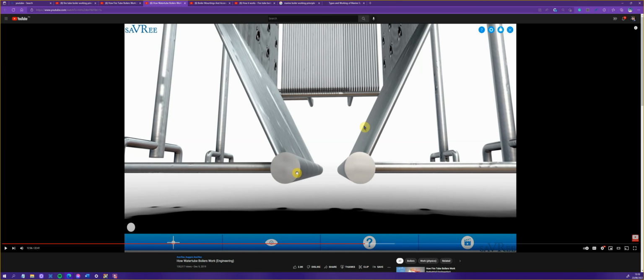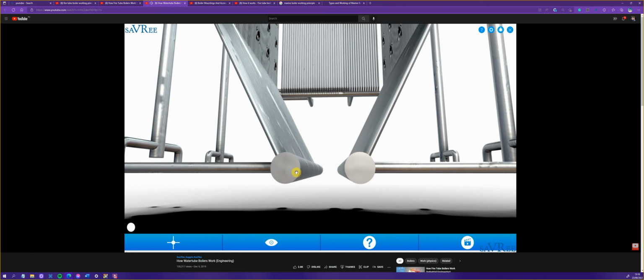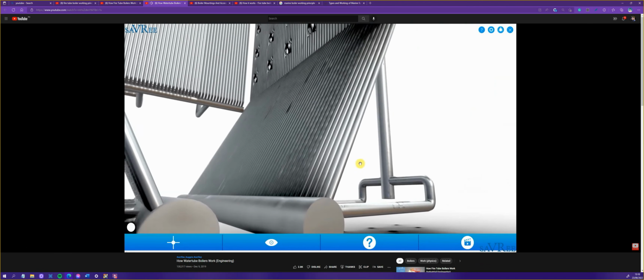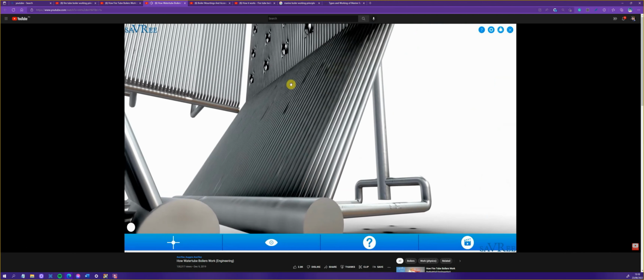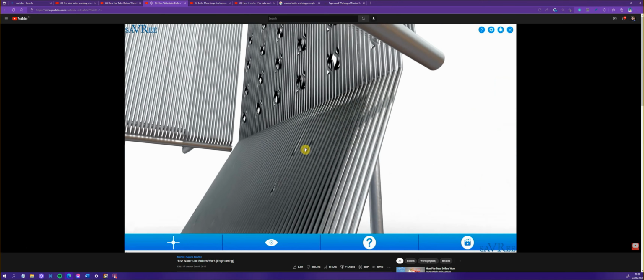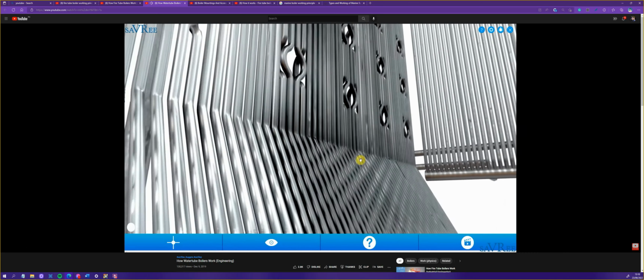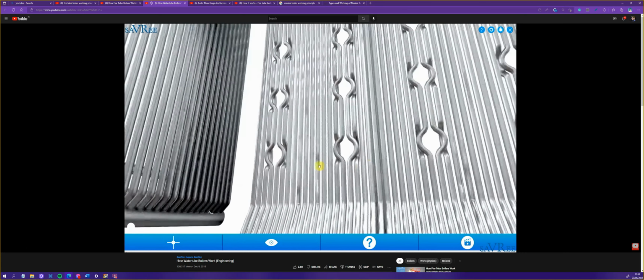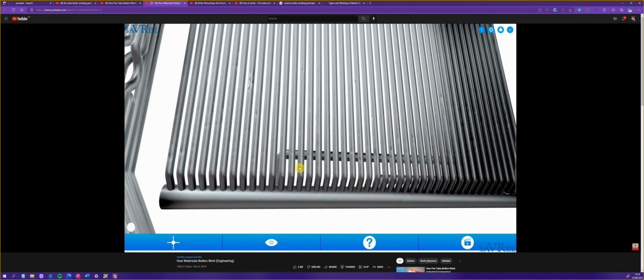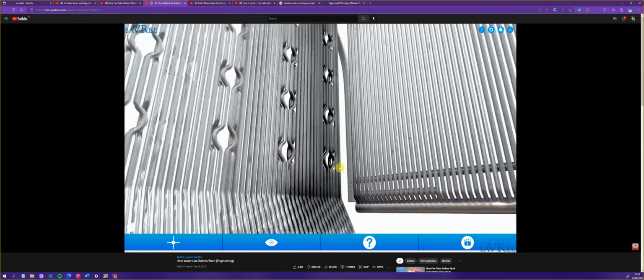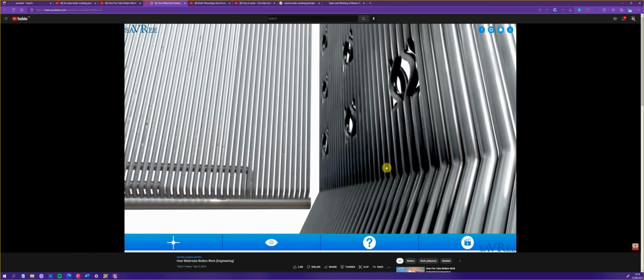So, steam drum. From our mud drum, we're going to send the water up, and see the pipes coming up here, the tubes, and we are now inside the furnace. You can see that we've got tubes on all sides. That is a side wall. That is also a side wall, and we also have a front and rear walls as well.